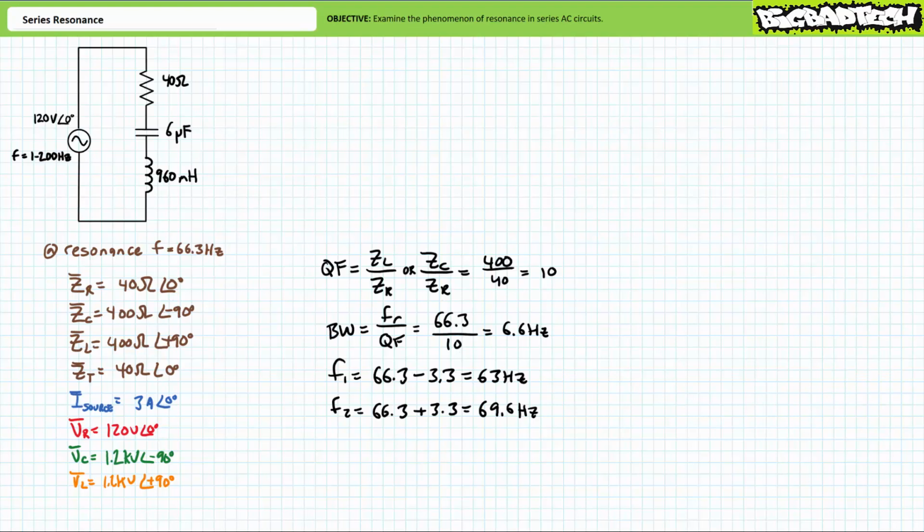However, we observed substantially different properties at resonance because this new circuit employed a smaller resistor, a smaller capacitor, and a larger inductor. For series resonant circuits, that's a surefire combination to increase the quality factor. At conditions of resonance, note the reactive components have much higher impedances than the resistor, and all elements experience a peak current of 3 amps.